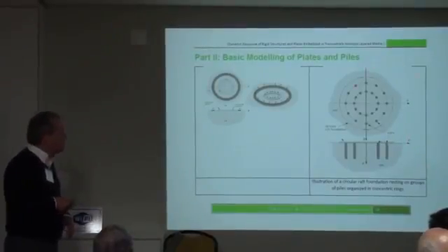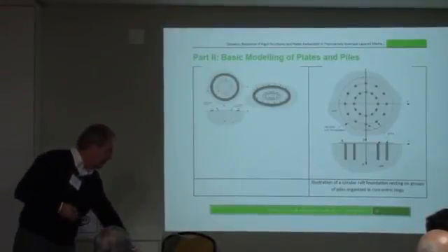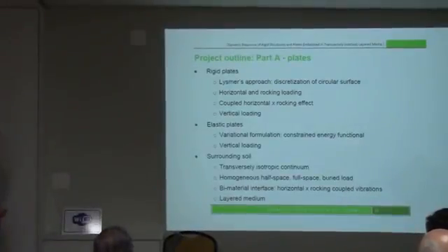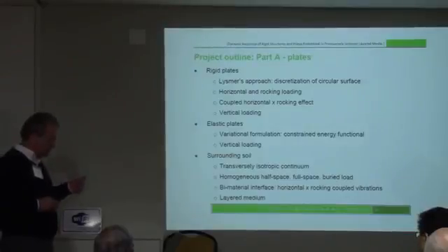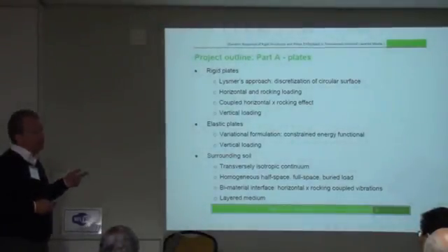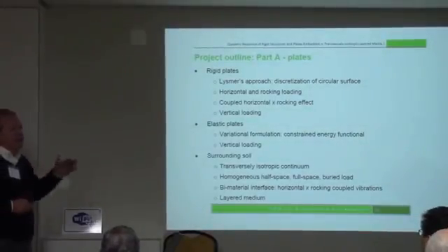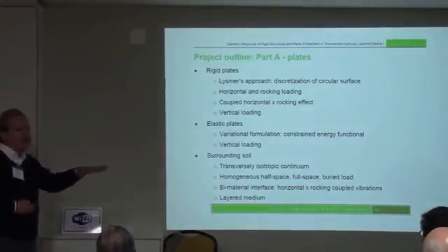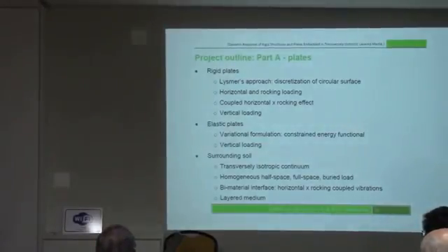So I'd like to say something about what we have done so far on the dynamics of the plates. We are working on piles presently and then on the coupling of piles. I hope to be able to present something about piles next year. So we have rigid plates, elastic plates, and the surrounding soil. For rigid plates, we use a very classic approach. I also want to say that the analysis here is stationary, in the frequency domain, and linear, because the displacements that we have over there as a vibration criterion are very small. So everything is within the linear range here, and I think it's acceptable for that vibration requirement.